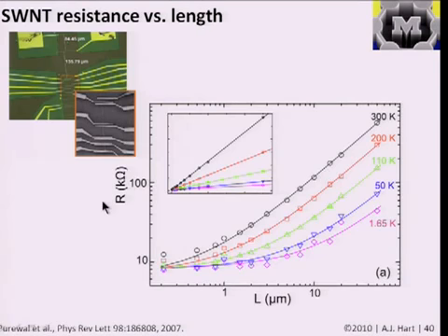So we are in the regime of classical diffusive transport where the nanotube obeys Ohm's law. Then the characteristic starts to change as you go down to a length where you see contributions from the combination of ballistic transport and diffusive transport, basically where the size of the system is affecting the number of collisions you have per unit length.